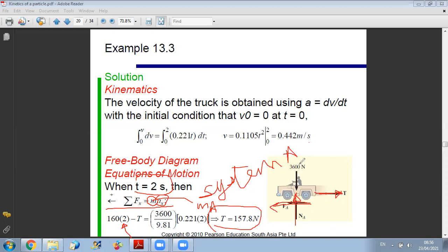Okay? So this problem is to tell you in general, they will not do it for you in steps, they will just ask you what is the coupling force between A and B. You should know that first I should take the whole system to get the acceleration, then I take A alone to get T. Now if someone did not notice and took A alone, B alone, C alone, you should write several equations, so you will get 3 equations, 3 unknowns.